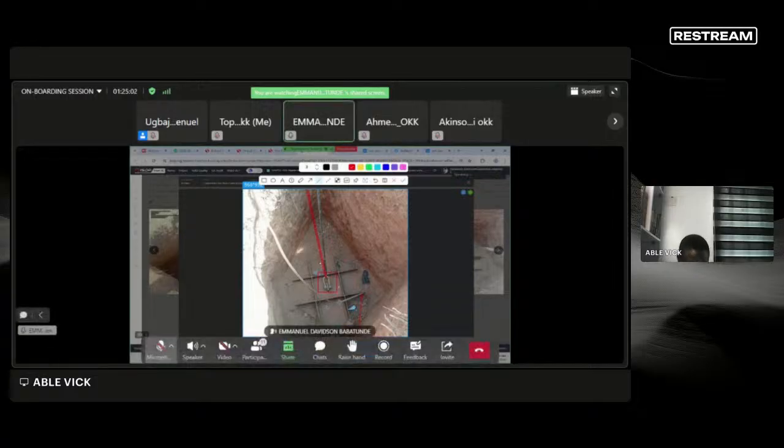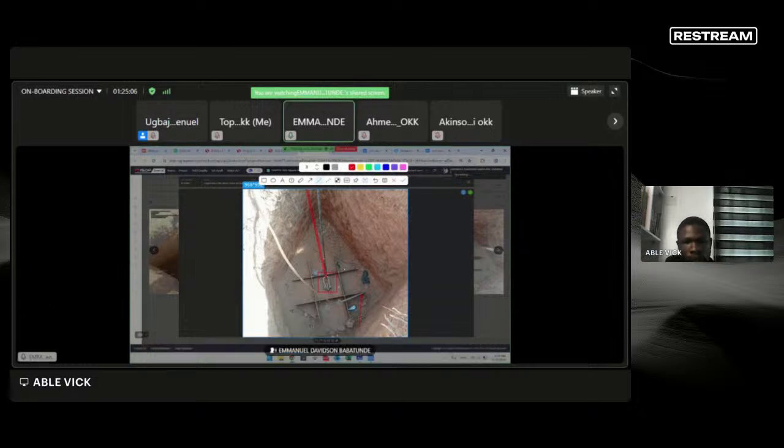If I see this picture, I can query the guy, and the guy can say, no, this is where the issue is, this excavation is not correct. He can even make a video for me and show me his alignment from the middle of the tower coming to this guide wire trench, and show that his excavation is already shifting away from the 5-meter line. If the person knows what he's doing, he can make a video to tell me, boss, that base plate installation is actually where my alignment is. Is my excavation that has the issue?